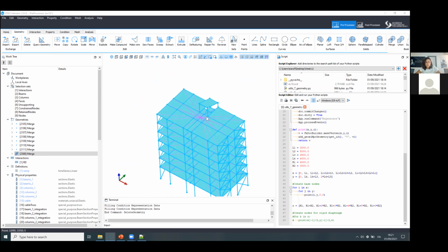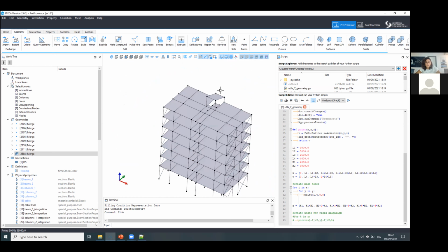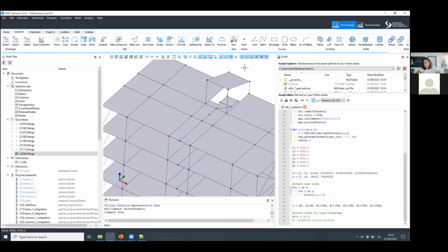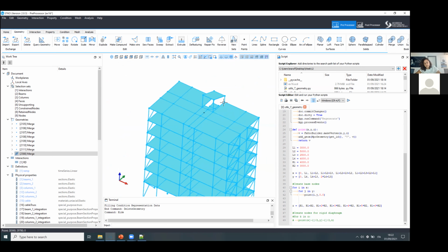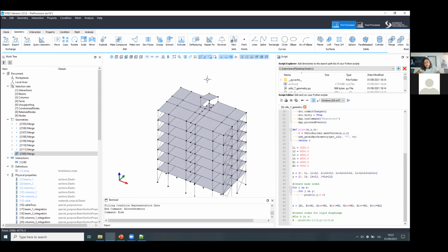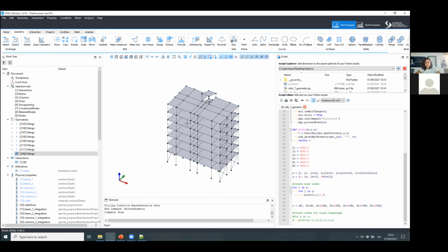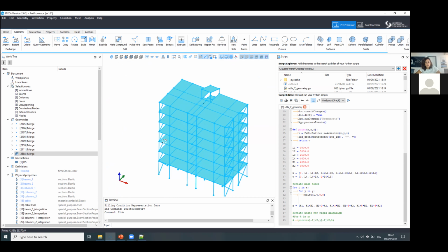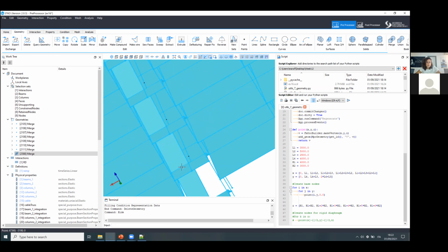If we just turn this interaction off for a minute, you will see that we had to add some additional lines in order to subdivide the slabs and obtain quadrilateral elements for our mesh. We need to remember that to these lines, for example, here in the center or here in the center of the ramps, we are not actually going to assign any property. And we have actually a system to do that in a very easy way.